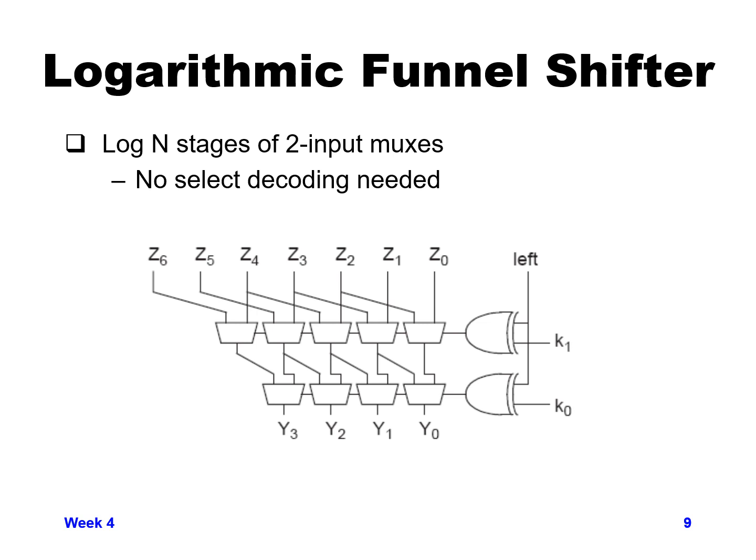And this allows us to do the shift. It might take a little bit longer going through 2 sets of 2-to-1 muxes, but the overall area of the layout that we're consuming is smaller, and again, this scales a lot better for larger shifters. So this in general is more the type of design we'd expect to see for larger bit values, going into 16 bits or 32 bits and above.